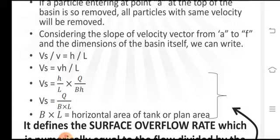Now here you can observe that this velocity, which is representing the horizontal velocity, we have already described as a flow per unit area. And that area is cross sectional area. So flow is expressed by Q, and cross sectional area is expressed by the depth multiplied by the width.